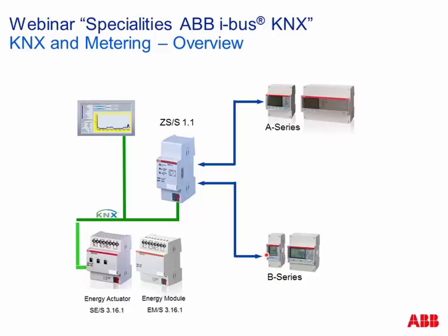And now here you can see our meter interface, which has this infrared interface on the right side. So we can put our meter interface tied together to our meter, and then we get all measured values from the meter to KNX. Inside this meter interface there is no logic or threshold, it is only to send all measured values from the meters into the KNX world.